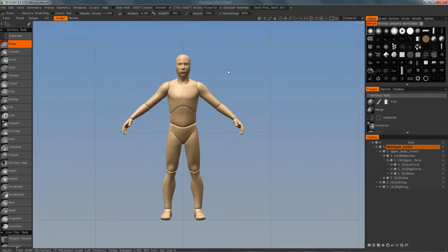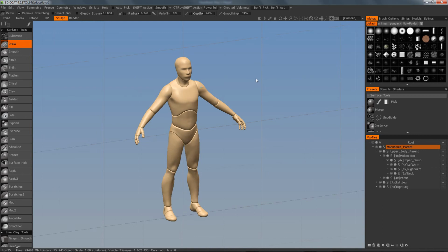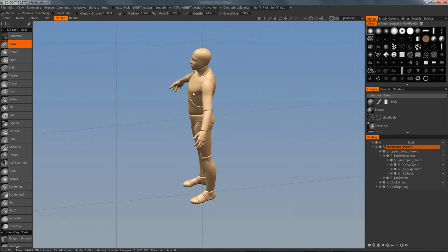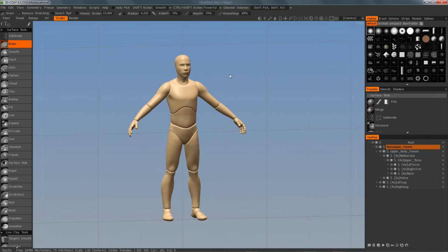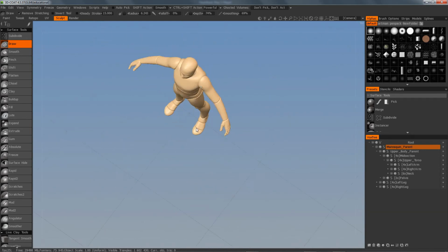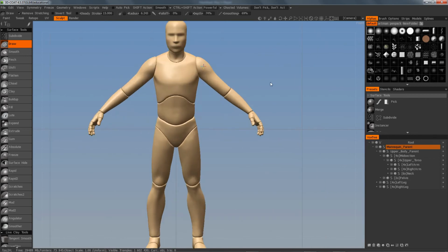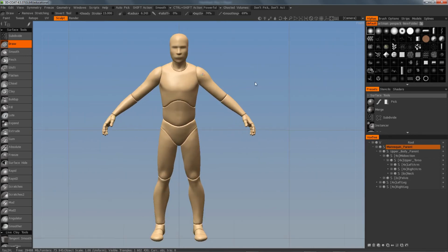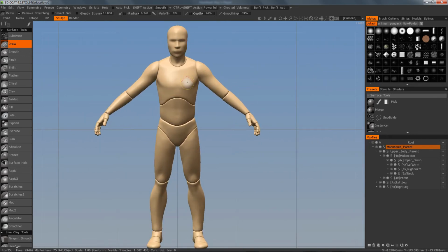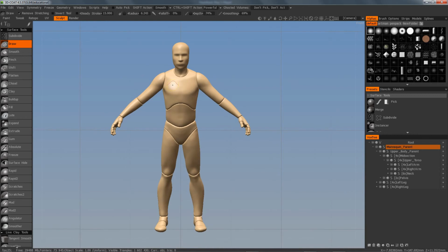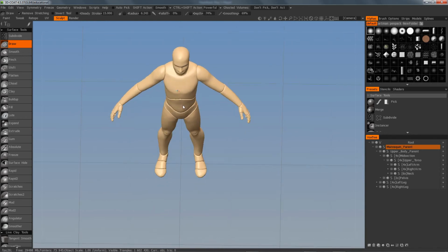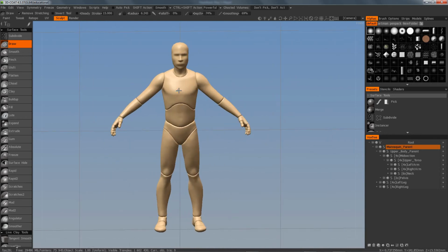Review, revolve. Left mouse, click and revolve. And this one you do have to actually touch the tablet. Zoom, right mouse, hover, left to right. Gives you zoom. Over the model, you have to hold down the Alt key. Same is true with revolve.